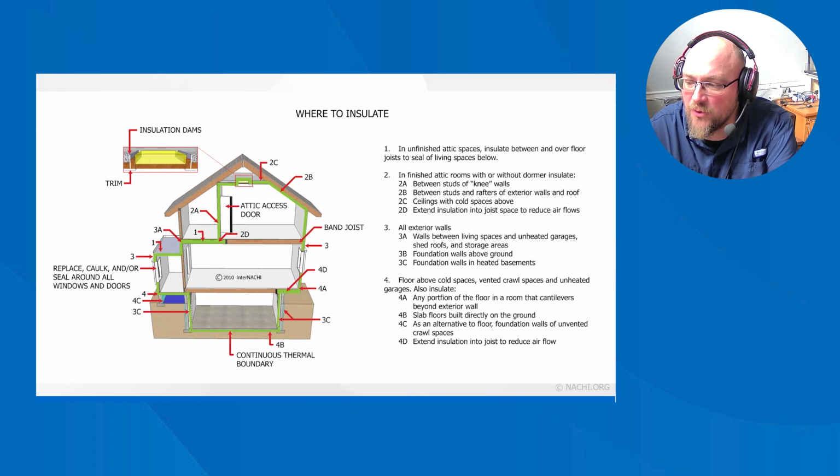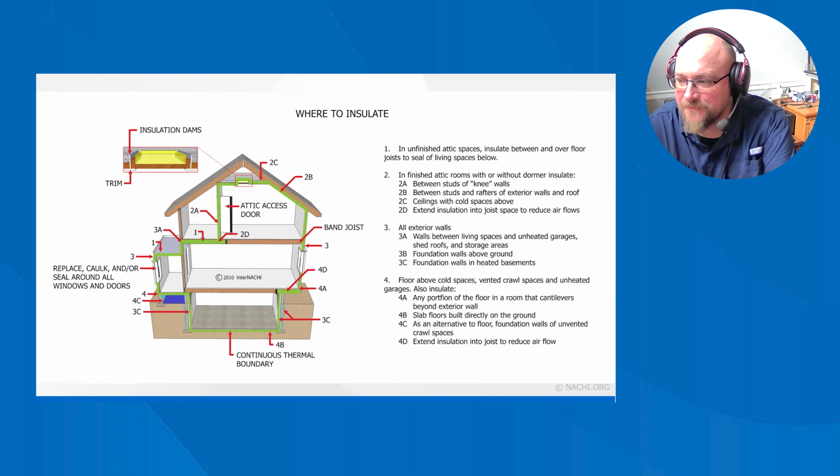Adding insulation in a mobile home is complex and usually requires special expertise. Adding insulation over existing insulation should not include a vapor diffusion retarder between the two layers.